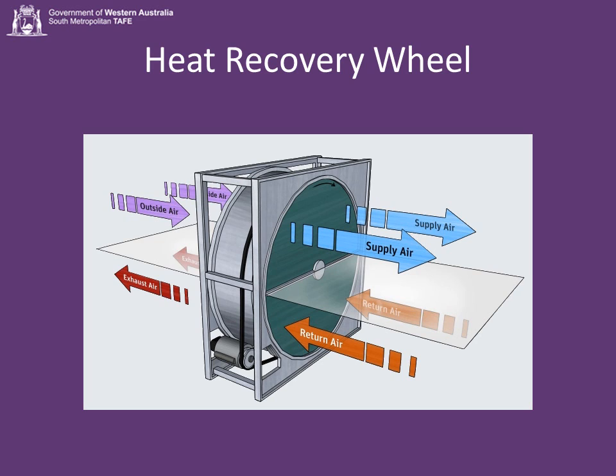If we are taking in outside air, and we have to take in outside air to supply fresh oxygen to the people in the buildings, then we have to get rid of some of the return air. That return air has already been conditioned. It's already been heated or cooled. We've put energy into conditioning that air. It's a shame to waste that energy. We use heat recovery systems, like heat exchangers or a heat recovery wheel, to recover some of that energy.